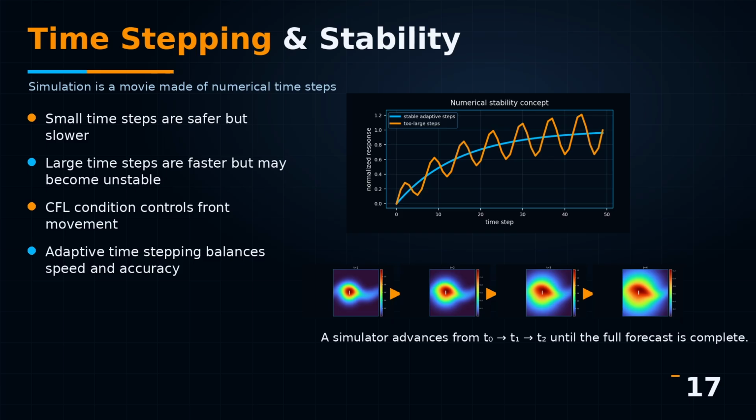The size of the time step is very important. If the time step is too large, the solution may become unstable or inaccurate. Sharp saturation fronts may be smeared, pressure changes may be poorly captured, or the nonlinear solver may fail. If the time step is too small, the simulation becomes very slow. Good simulators often adjust time step size automatically, smaller steps during rapid changes and larger steps when the system is stable. This slide shows how time stepping creates a sequence of reservoir states.